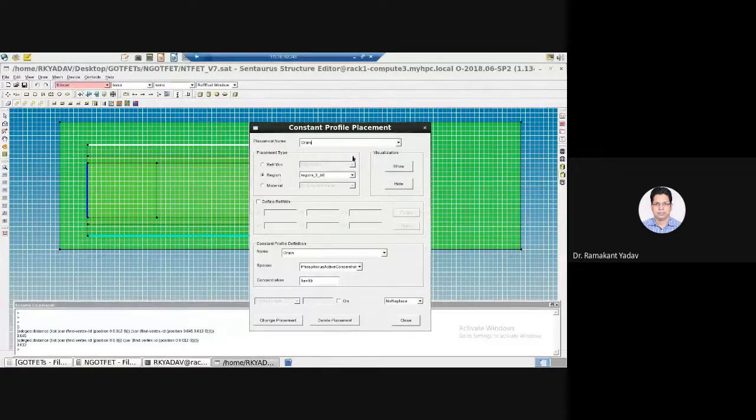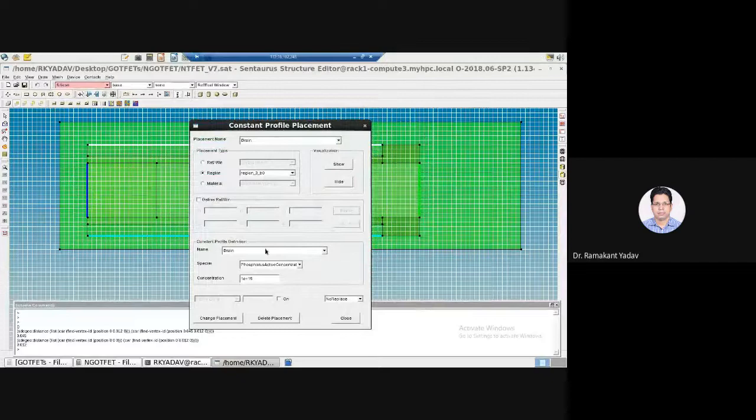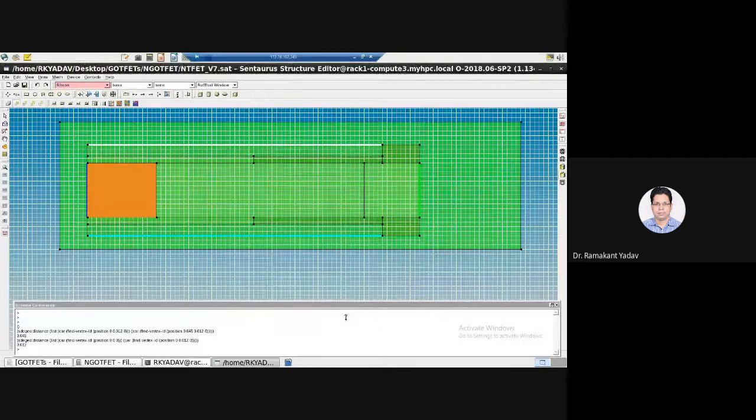So this is the drain region. Okay, so drain is N type. Okay, so this is N type. Now if I see, the source is P type. But what we have seen in the MOSFET, drain and source regions are the same type, doped with the same type of dopants. So that is the primary difference between the MOSFET and TFET.